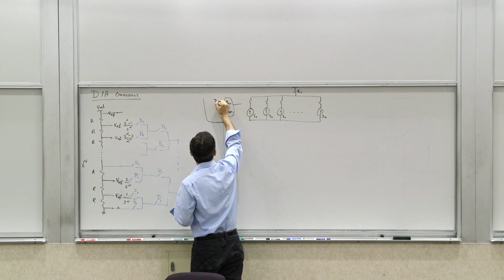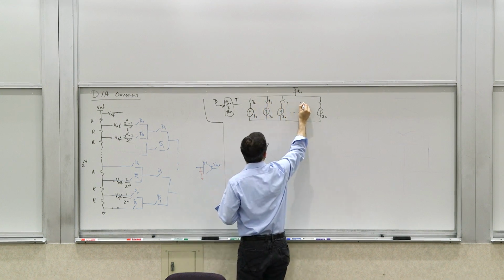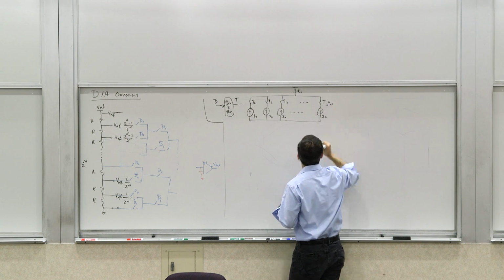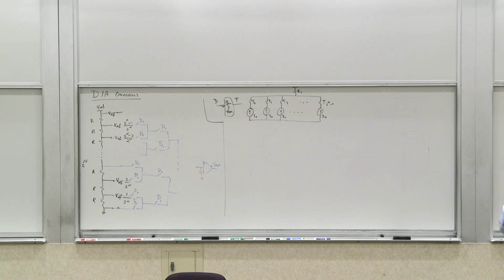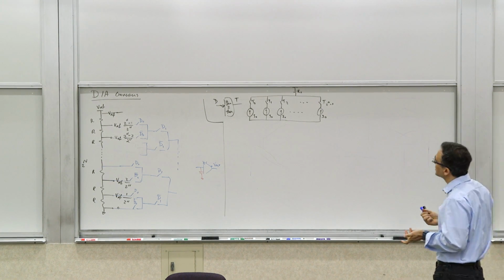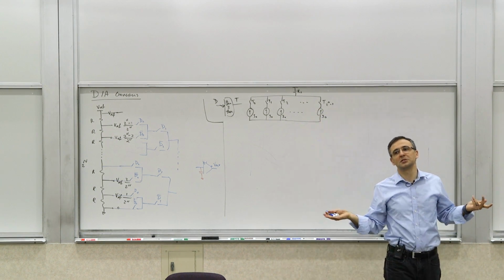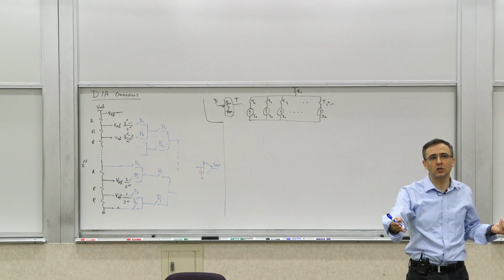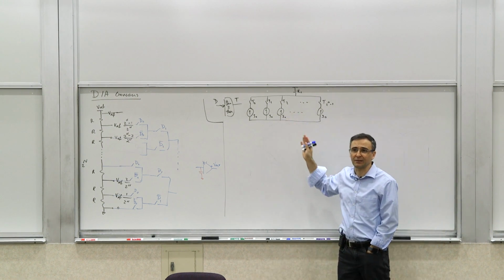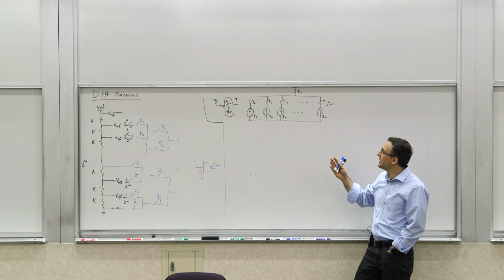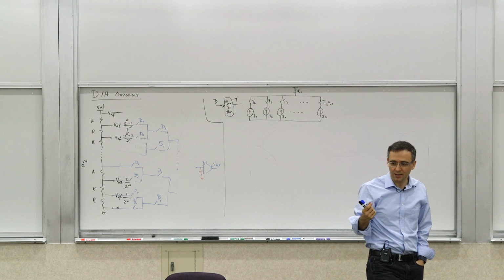And then your digital input comes in, you generate thermometer code, so you basically get T0, T1, T2, all the way to T2 to the power of n minus 1. And you just turn them on, you just drive current into a resistor. And now if you have a capacitor there, that's fine, because now your time constant, assuming these are ideal current sources, is determined by that RC. So you just drive the current into that, but you have drive capability because you have current sources. These are active, right? You can drive it. So this is a really simplistic D2A, right?